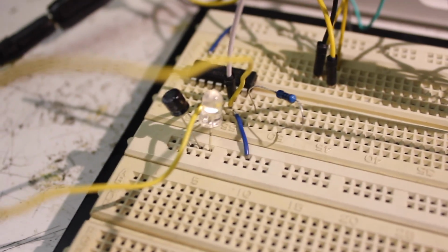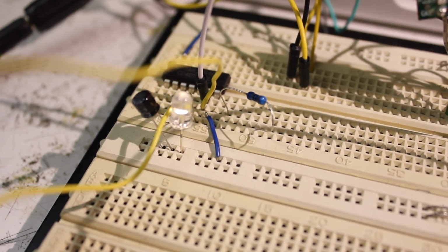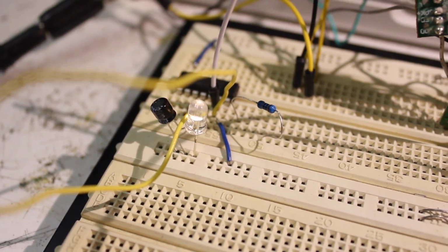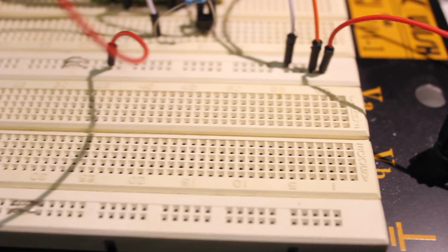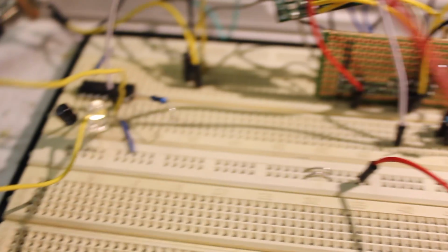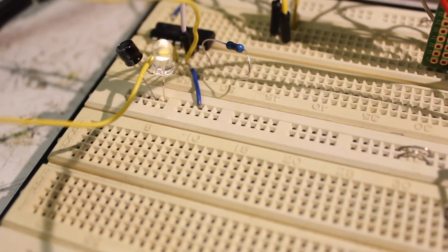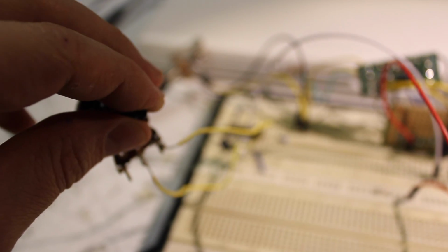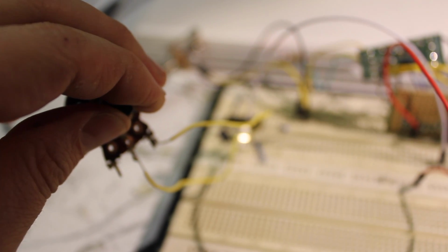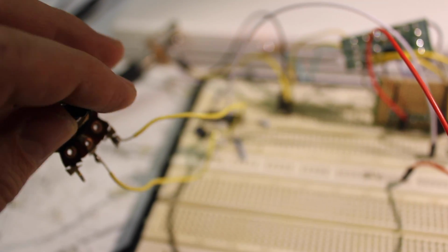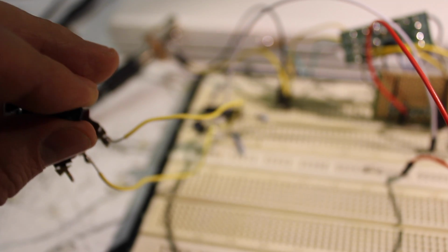Here's just a simple 40106 LFO pushing, turning on the transistor that turns on the sound, the same as you would push the buttons on the toy. And you can adjust the speed just to test out the circuit with the transistor.